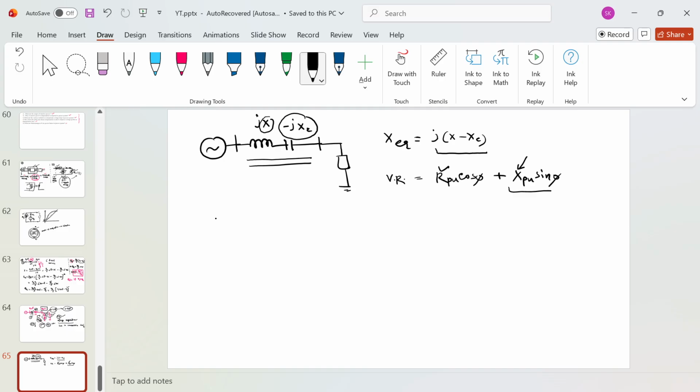And also, if you think from the load circuit point of view, let's say you have an inductive load connected here, you can connect a shunt capacitor to supply the reactive power that will improve the power factor. That will reduce the transmission line losses, and you can say that will improve the voltage regulation. So you can either connect a capacitor, or you can connect a synchronous condenser.